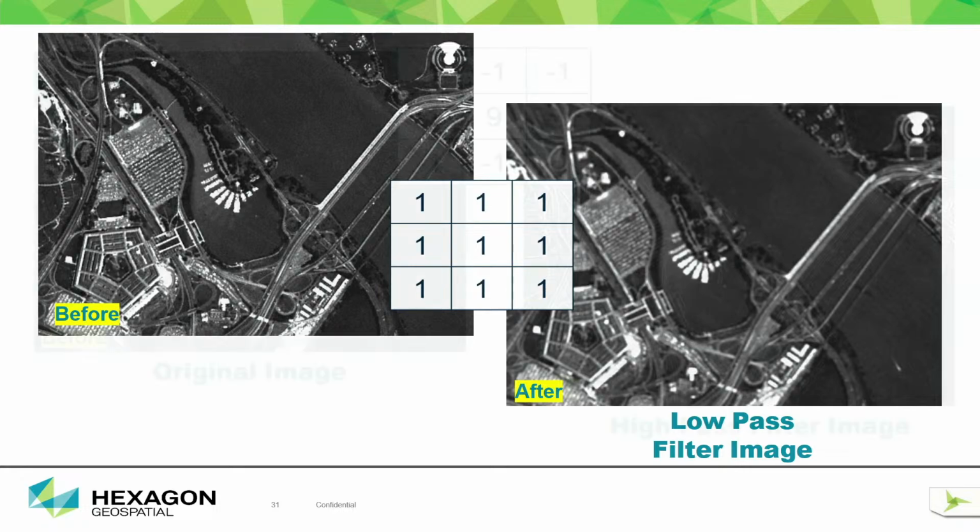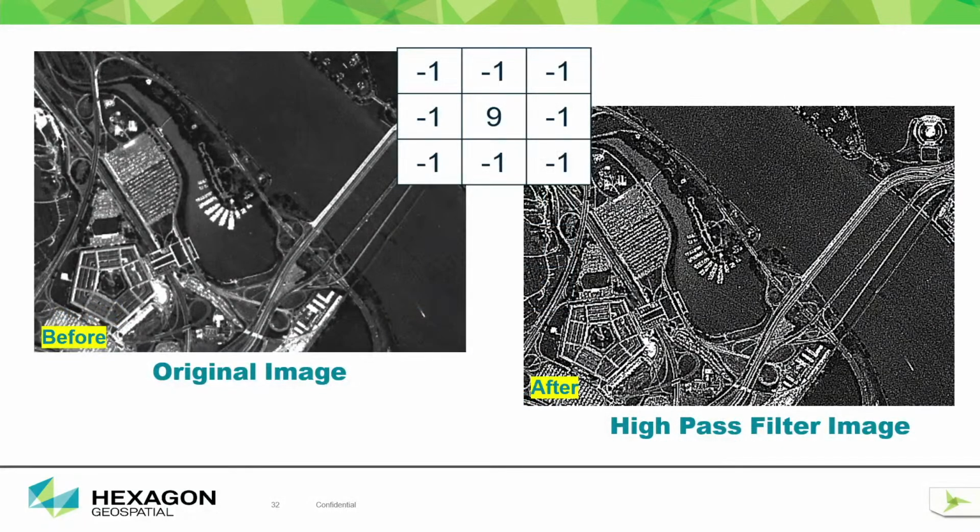In the same way we are using the low pass filter. Here you can see that those having the highest reflectance values have been minimized, so these features have been highlighted. So it will be easy to identify from the images. Now you can digitize or extract this information easily from the satellite data, and that is the main funda for using the low pass or high pass filter. So the high pass filter basically we use to extract roads. If you have a road network or any linear network, at that time you can perform the high pass filter.